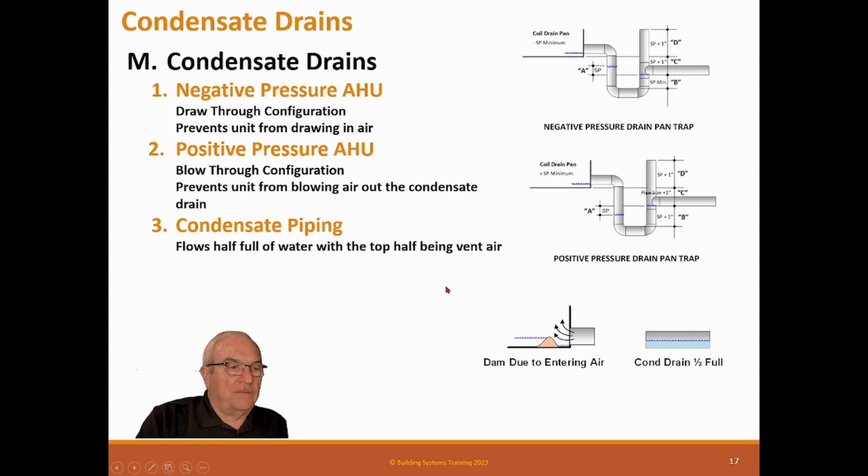I have seen jobs that have millions of dollars in damages because of one condensate drain. They backed up, caused growth, caused IAQ problems in the building, lawsuits in the building, all because of a $25 trap. Some contractors say, I can't build your design because I don't have enough space to do that. Well, sorry, but you have to have. So you have to jack up the air handler, bigger sleepers on the air handler, or drill a hole in the floor, but you got to have the trap. It's not optional.